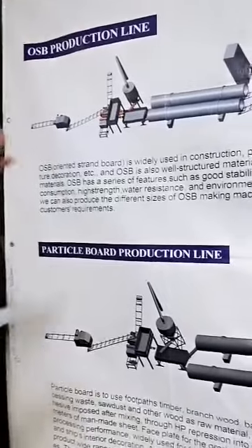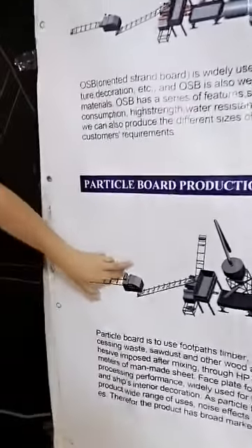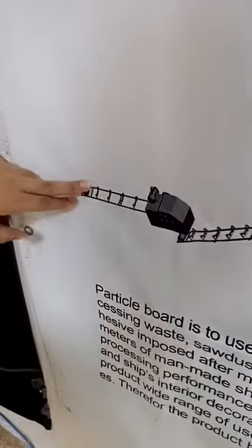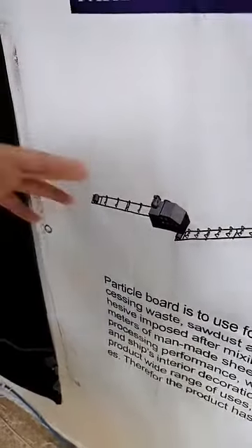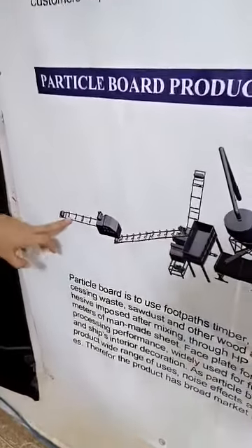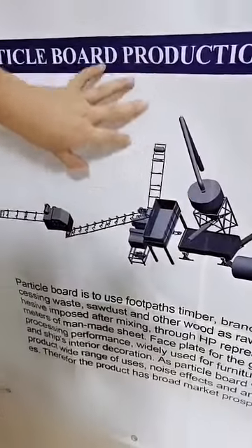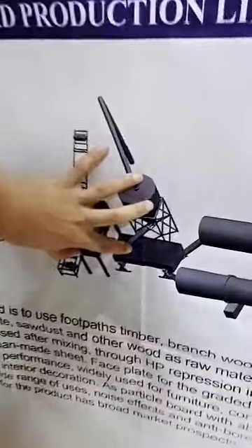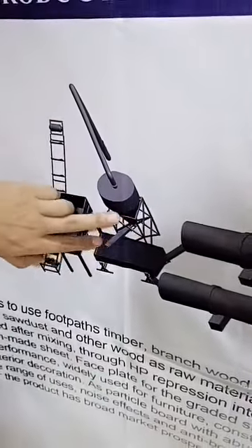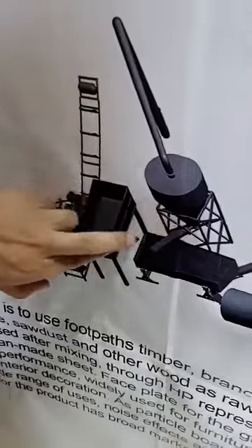At the very first, before this crusher or before this chipper, in this transfer we also have a metal remover, to remove metal from the wood or from all the materials, like some nails and maybe some cans. There's a metal remover, and also from here there's another metal remover. Then you can see from here, all the materials go to this. We call this the vibration screen.